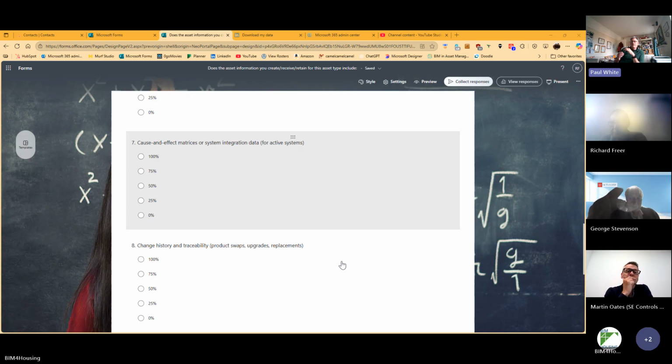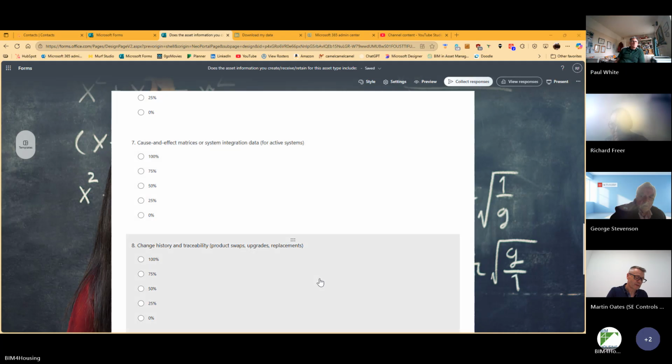most of us would say it's fairly obvious what should happen, but there may be separate parts of the design where there's sub bits of the system that do something slightly different. I've literally just been looking at one where you've got a neutralizing gas, gas suppression system, where some of the dampers have to be reopened again to get rid of that gas. Now that's very specific to that design, and if you didn't know that, you'd be going, well, why are these opening? Do you understand what I mean? So these are the sort of things that you see.